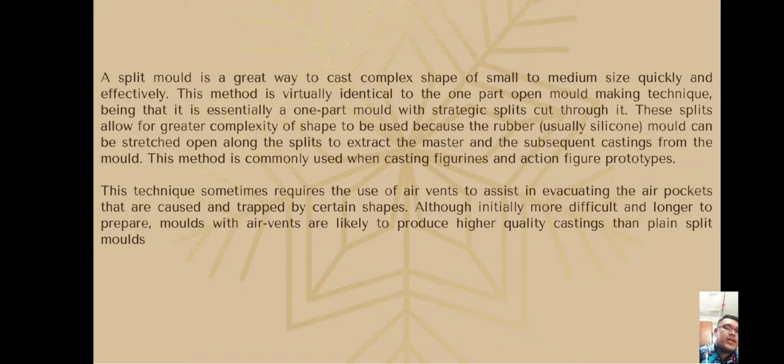This technique sometimes requires the use of air vents to assist in evacuating the air pockets that are caused and trapped by certain shapes, although it is initially more difficult and longer to prepare. Molds with air vents are likely to produce higher quality casting than plain split molds.